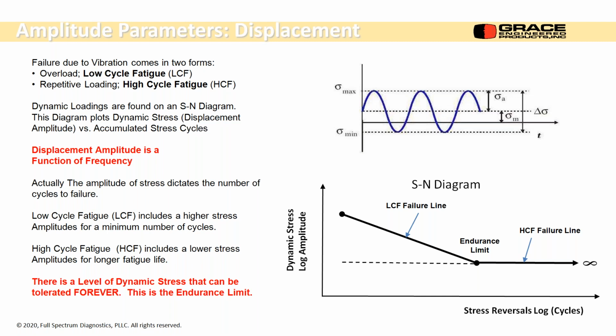You get a lot of low cycle fatigue from that big torque and that change in temperature really quick. So the overload capacity, these things really shoot to a high level when you turn them on. There's no soft start. They were never designed for that. And you start to get low cycle fatigue problems. And then you have to start limiting how many times you can do that a day or a shift before you're going to cause real big problems.